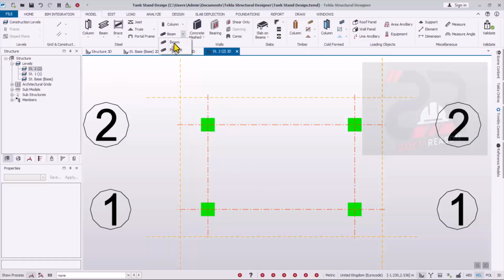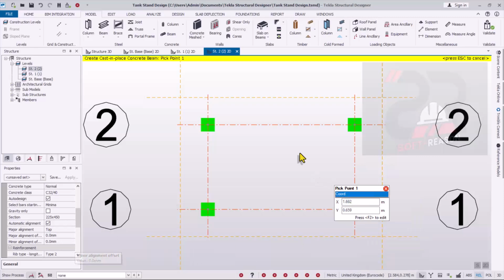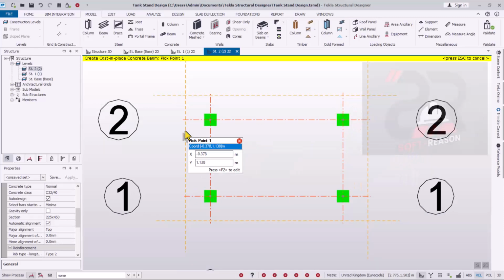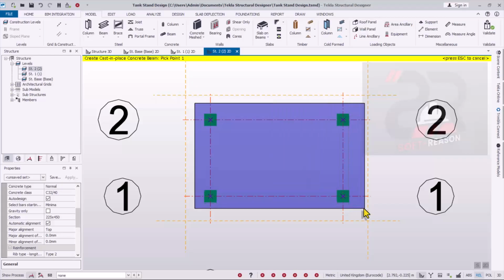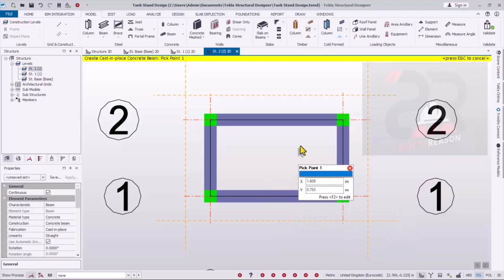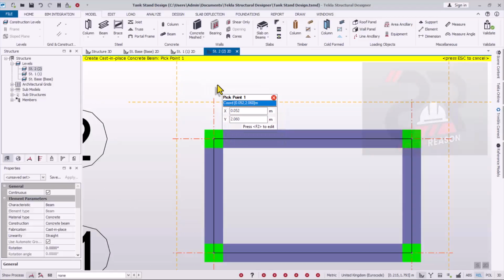First, you click in this provision, pick on the beams. You can check the properties of the beams right here. Everything is good right here. So what we need to do now, just do a grid line intersections from here to actually place the internal beams. All right, so for the cantilever beam, you have to be careful in placing it, otherwise you will not be able to apply the cantilever function properly. So watch me do it and watch me closely.